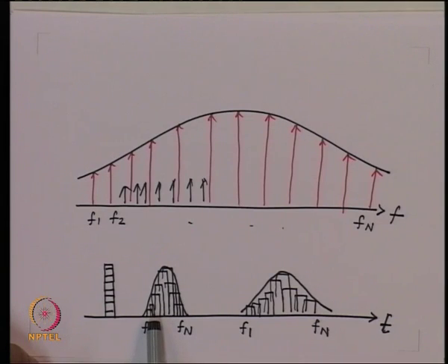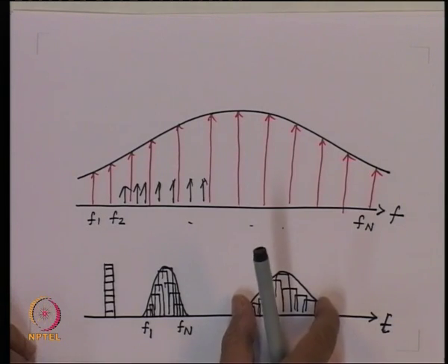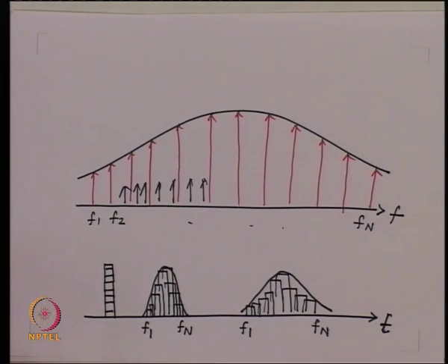Also, the pulse broadening is directly proportional to the distance travelled, because more they travel, more will be the difference in the distance travelled by the pulses because of difference in velocity. So, more will be the pulse broadening. So, we have this pulse broadening, which now depends upon the distance travelled on the optical fiber, and it also depends upon the spectral width of the carrier.